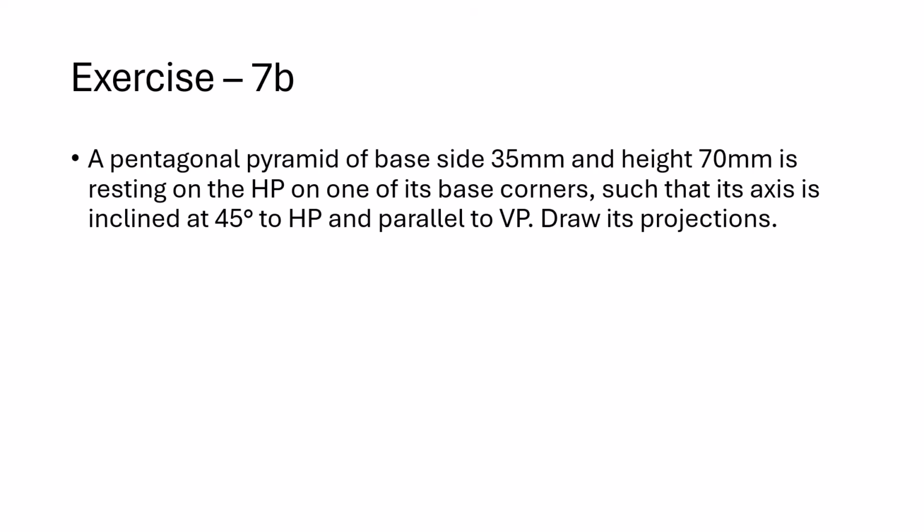In this video, you will learn how to create a pentagonal pyramid whose base side is 35 mm and the height is 70 mm, and it is resting on the horizontal plane on one of its base corners. Whenever it is resting on a base corner with the axis inclination 45 degrees with HP, while we are making the pentagon, make sure the corner is on the right hand side. So whenever we are creating a pentagon, make sure a corner is on the right hand side